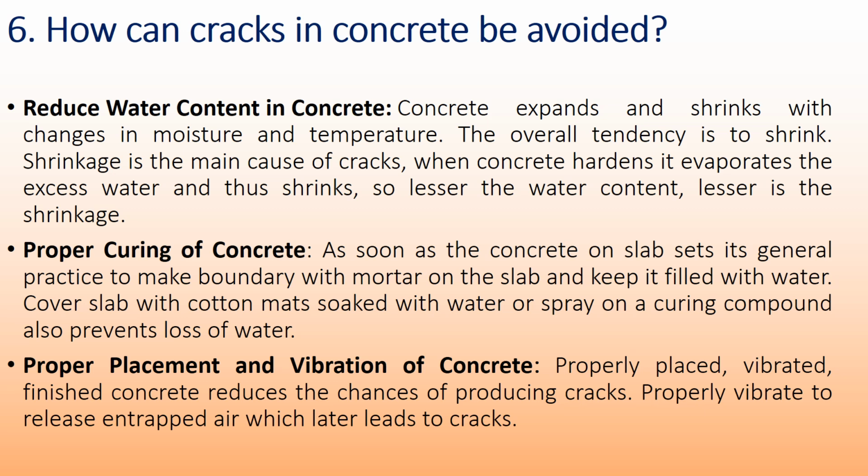Proper curing of concrete. As soon as the concrete on the slab sets, it's general practice to make a boundary with mortar on the slab and keep it filled with water. Covering the slab with cotton mats soaked with water or spraying on a curing compound also prevents loss of water. Proper placement and vibration of concrete. Properly placed, vibrated, finished concrete reduces the chances of producing cracks. Properly vibrate to release entrapped air, which later leads to cracks.